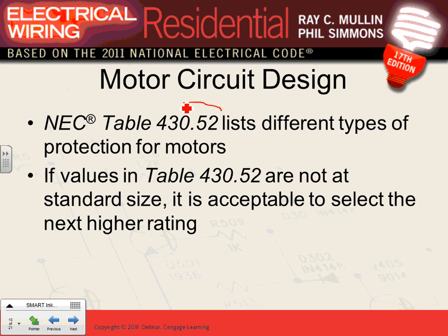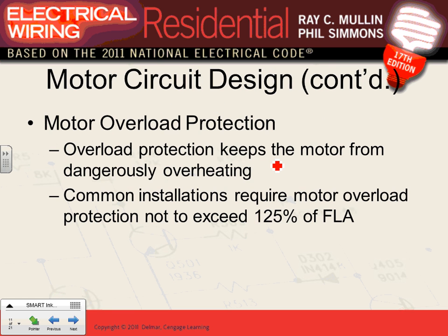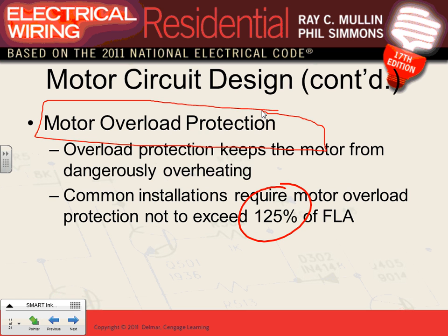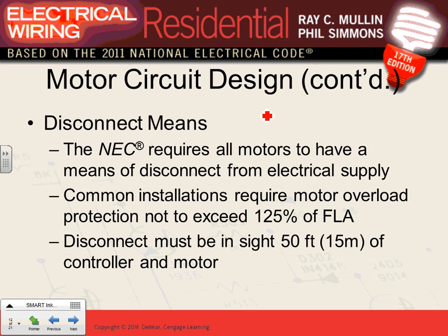These are the articles that size the overcurrent protection device for motors. I will come to this table later on and do a couple of sizing examples. When we have motors, I'm going to do an example about overload. For motors, you have to have an overcurrent protection device for short circuit and overload to protect the motors because they're so expensive. The overload, typically we size at 115 to 125 percent. I'm going to have an example of these in a second.